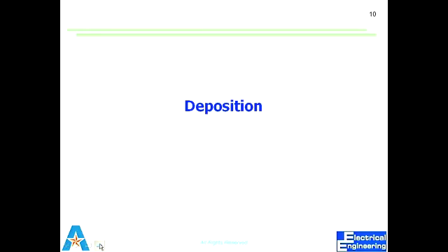With etch we remove things, with deposition we deposit materials. We can deposit a very large range of materials. We can deposit amorphous materials, we can deposit single crystalline materials, while using special processes where we have something which is already crystalline, we can deposit material on top of that in crystalline form.